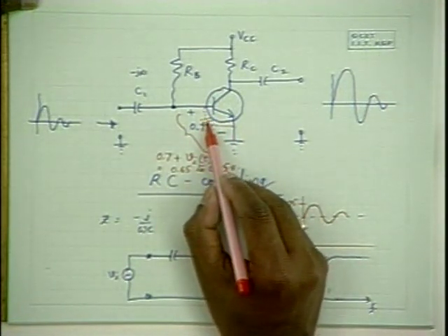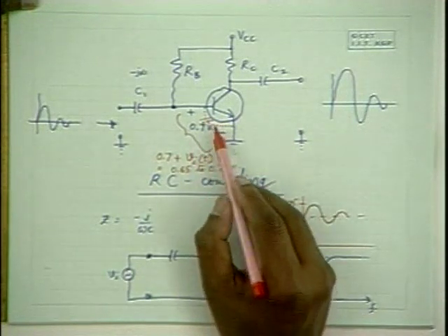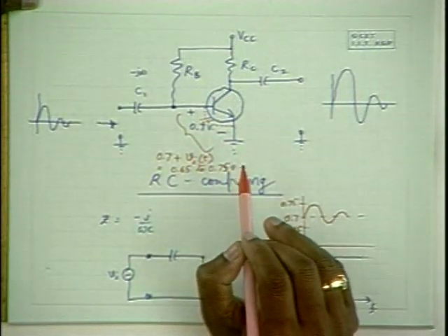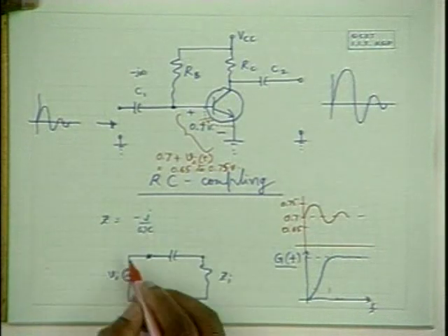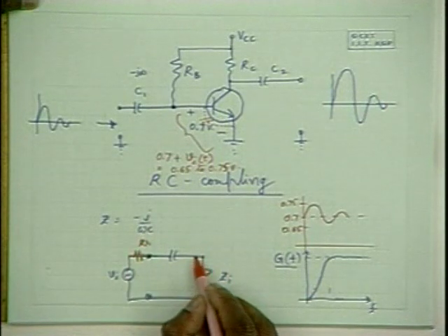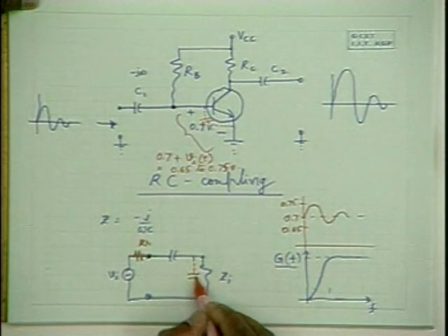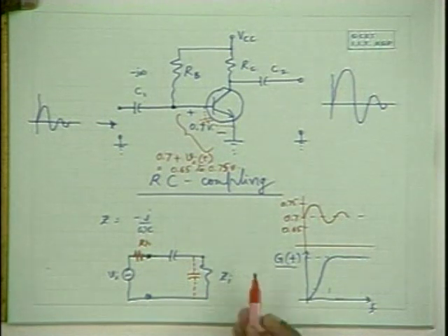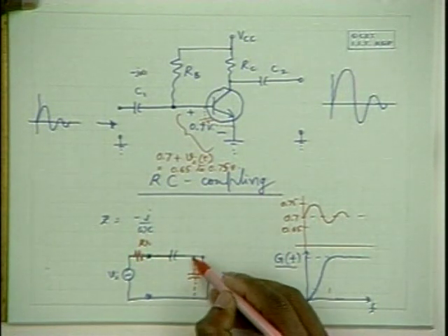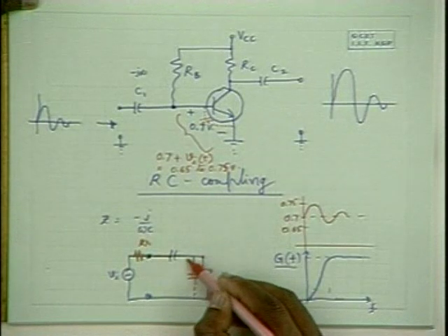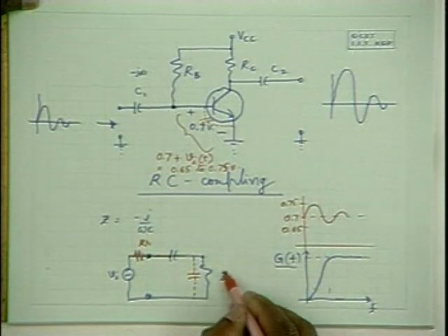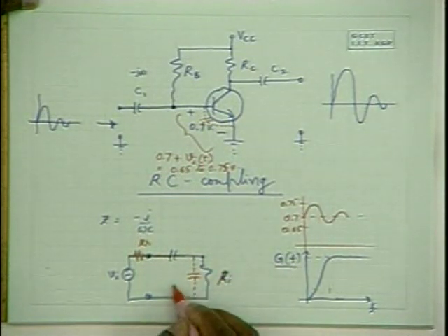And these capacitances are of the order of picofarads, and these are negligible at low frequencies, therefore we do not talk about them at low frequencies. But at high frequencies, when you have of course a source resistance also, these junction capacitances become effective and they short circuit. So these capacitances make this Zi smaller than Ri, which is in parallel with this capacitance, and that is Zi.